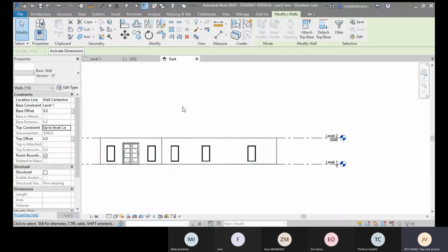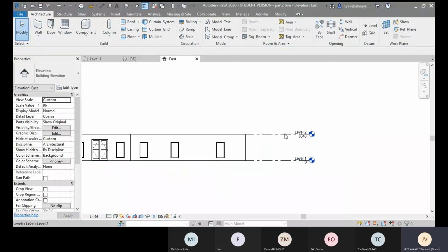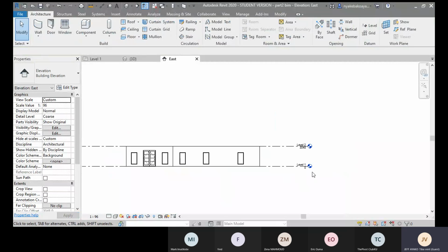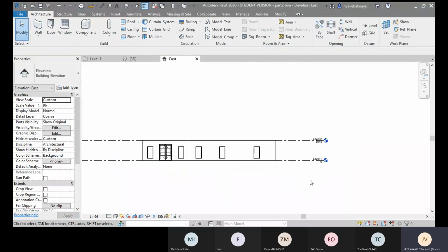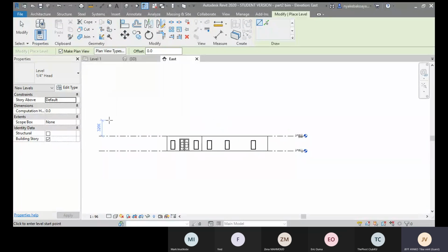So when you click on level 2, it goes down and flashes with that level there. So this is about levels. I also explained how you create levels. To create a level, you just come here on your ribbon under the architectural tab, where you have what is known as the level here. So you click on level, and that command is selected.